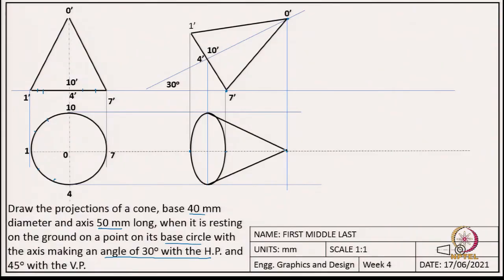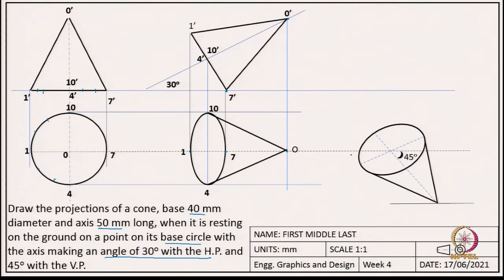Okay. So, first let us draw the top view. Now, we identified it is at an angle of 45 degrees. So, we first draw the ellipse, and then, by the height of the cone, we capture the apex, and once you capture the ellipse and the apex, you can draw these inclined lines to complete the cone. Okay. So, in this step we are done with the top view.